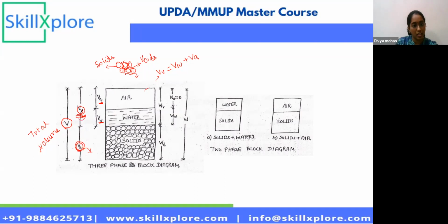While compacting, the volume of voids reduces, and while loosening the soil, it increases. So throughout this chapter, we can use the volume of solids as a constant parameter while calculating. It's a huge factor to consider while solving problems.